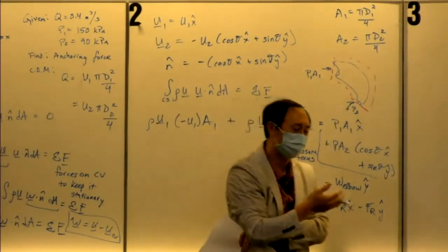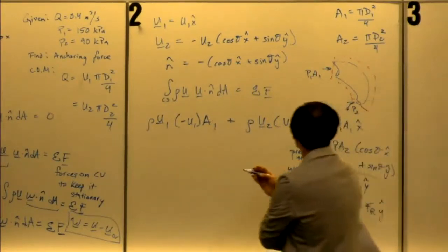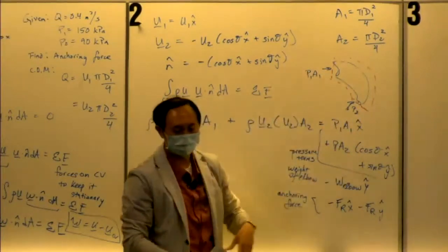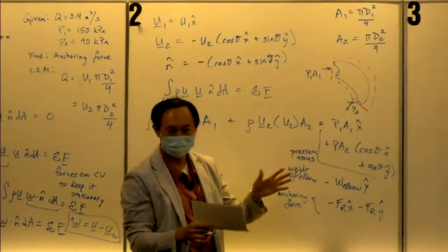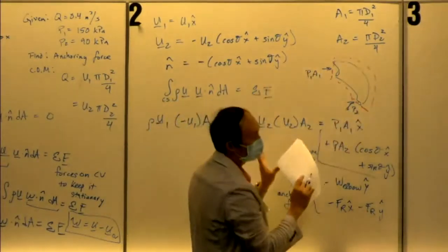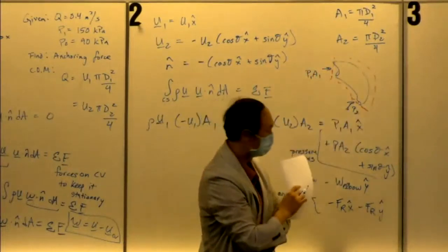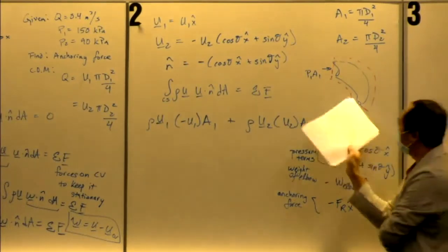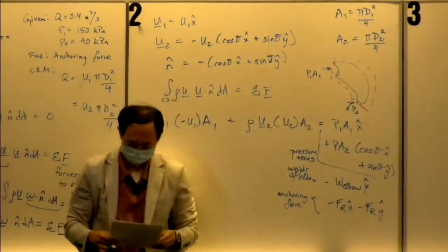From Bernoulli's equation, anytime you got a flow, anytime you got speed, you're going to have pressures. The way to imagine it is, you have this pipe fitting and this fluid going through. Imagine you just took that pipe fitting out and replaced it with a block of ice, just momentarily. Well, basically, just the pressures alone would send that block flying to the upper right. Just the fact that fluid has a positive pressure at both those ends. Okay. Thank you. That's the way you think about it. And if you go back to statics, I think they have a similar definition for when you look at forces.